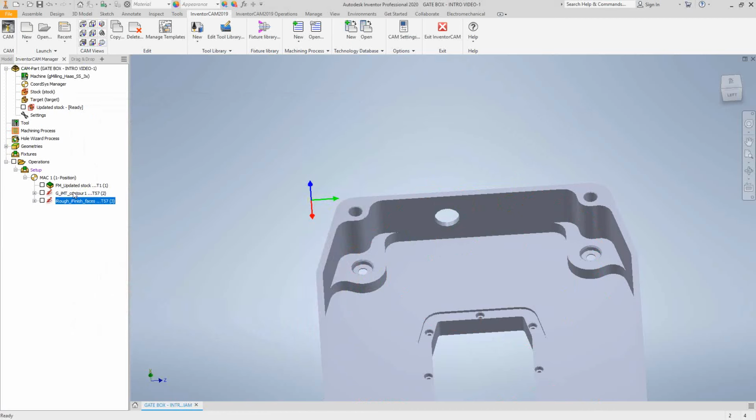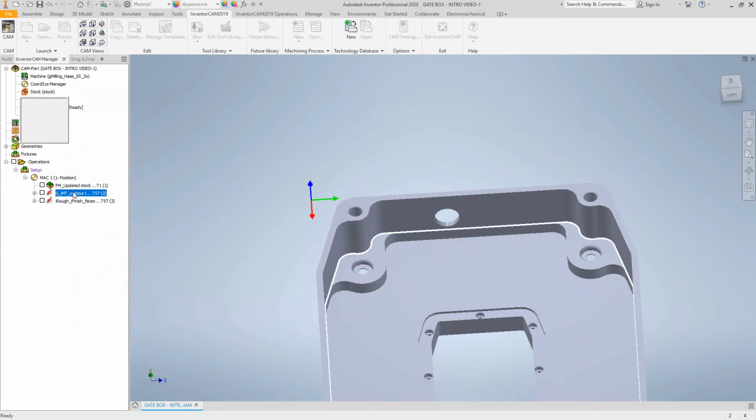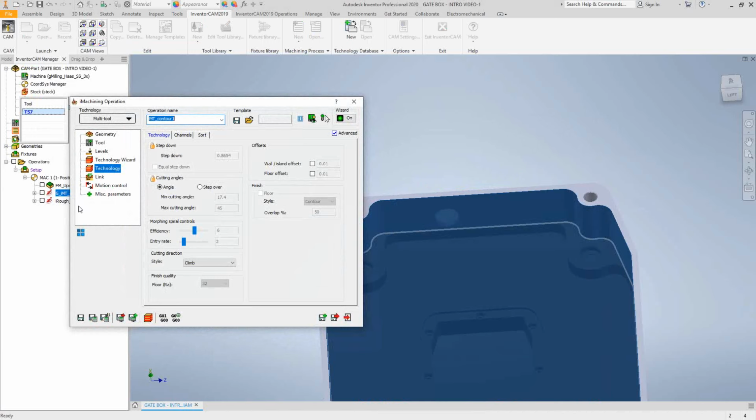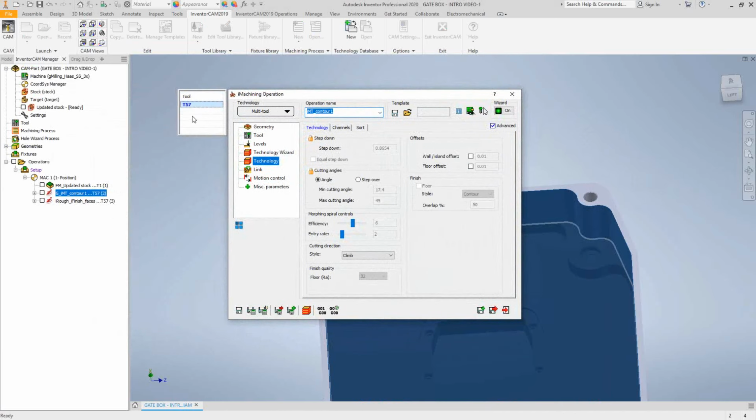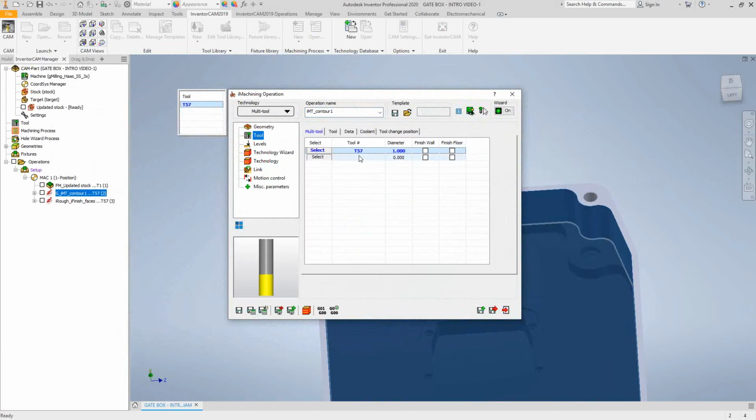Now, let's take a look at some of the other options inside of SolidCAM's 2D iMachining. So I'm going back to the original pocket, and I didn't mention it, but there is actually this little floating window here, and that is because we have it set to Multitool. This exists in both the 2D and the 3D versions of iMachining. And the reason Multitool is here is if we go to the tool table, I can actually add multiple tools and they auto-generate what's called the rest operations.